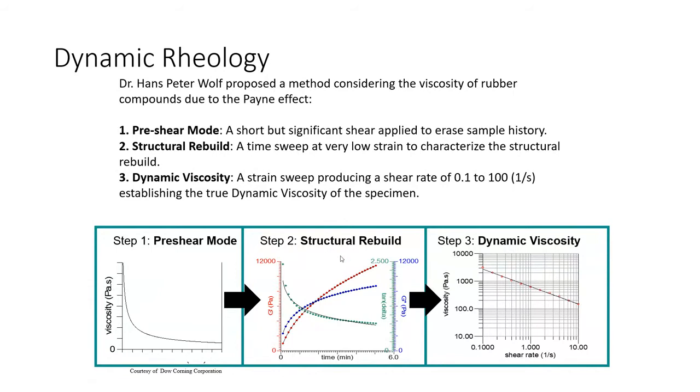And then once we've mimicked what the injection machine does, screw and barrel, the pseudo quasi-steady state process, then we can run a dynamic viscosity sweep and get to the true viscosity of the material. Again, a very linear performance. I'm showing from 0.1 to 10 reciprocal second shear. This is in log fashion. And so we run this style. Now, the specific programs around this I'll be going through. This is just kind of a 10,000 foot view of this.